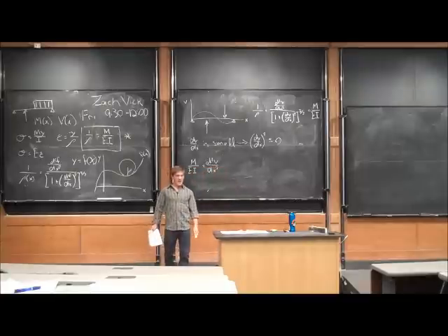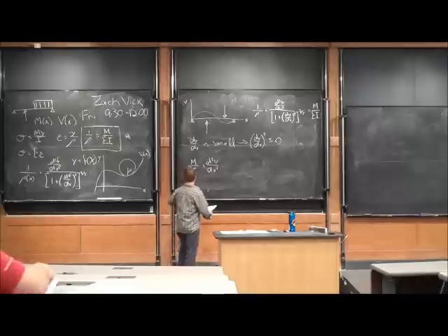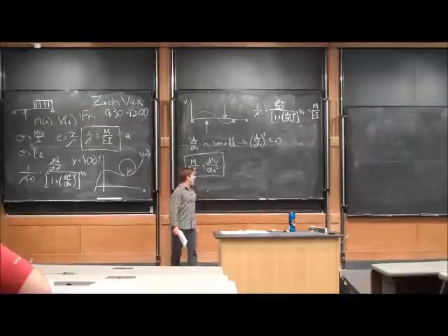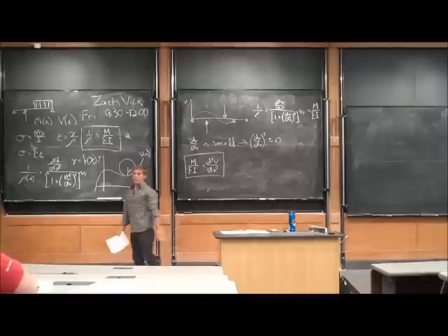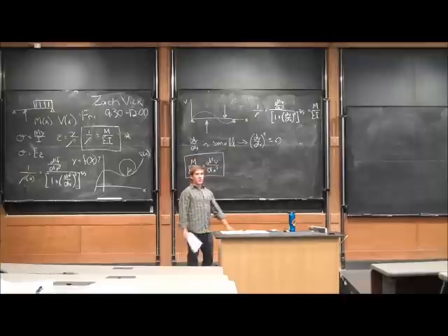And that's our basic equation that we're going to look at for at least the first half of class today. So this is a very important relationship in proving how beams will act when given a specific loading. Because we can look at an arbitrary loading, find what the internal moment in that beam is as a function of x, and due to that, we can find the deflection at every point in that beam.